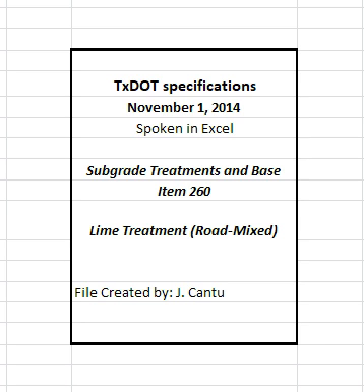4.3 Application of lime. Uniformly apply lime using dry or slurry placement as shown on the plans or as directed. Add lime at the percentage determined in section 260.2.6, Mix Design. Apply lime only on an area where mixing can be completed during the same working day. Start lime application only when the air temperature is at least 35 degrees Fahrenheit and rising or is at least 40 degrees Fahrenheit. The temperature will be taken in the shade and away from artificial heat.